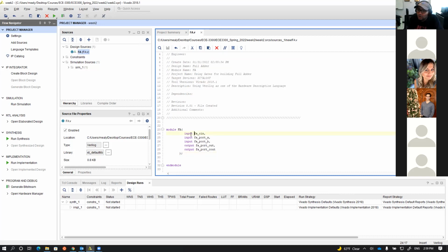Anyway, be sure the inputs are wires. The tool embeds this information called wire, and it didn't write it for you, but in reality, it's a wire. I can write wire like this, which is the type of the thing. Is it going to be a wire just passing something, or are we going to be storing? If it helps to store, it will be REG, register. Sounds good? So any input is a wire for us, but we don't need to write it because the tool recognizes it.